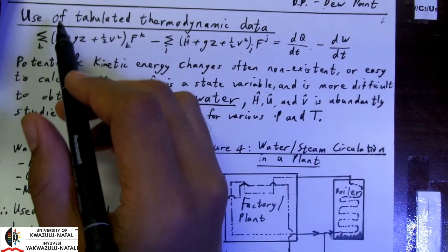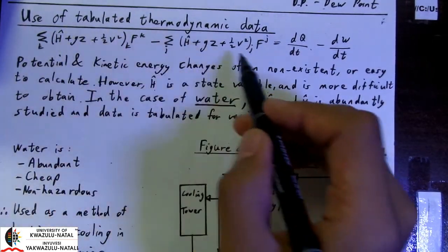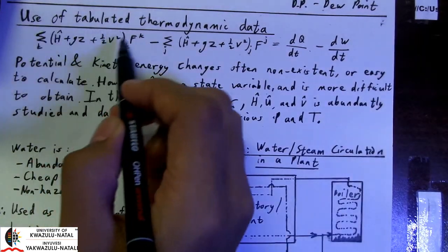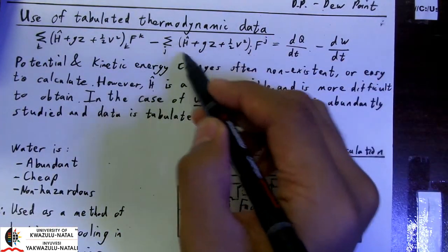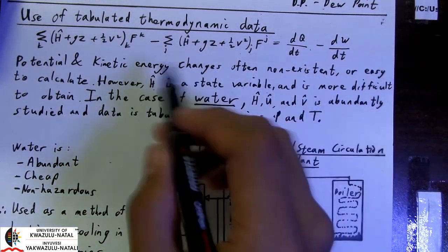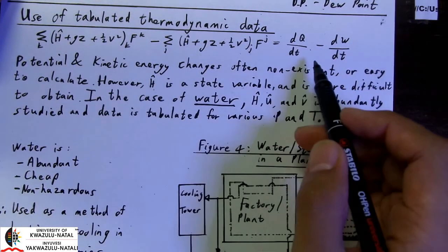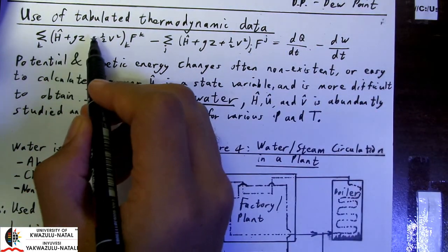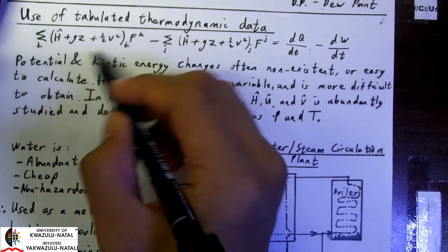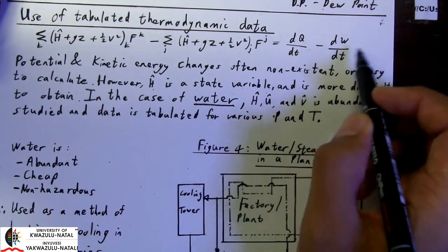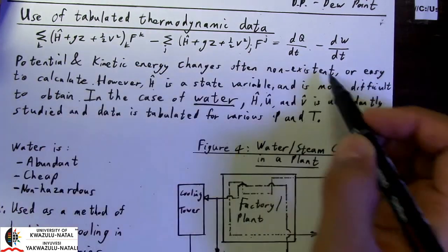So let's revisit our steady state open system equation, where we have our inputs minus our outputs equal to accumulation, and at steady state, of course, accumulation is 0. Simply shifting around our terms for our input flow and our output flow, as well as our energy input and work output, we get the following expression.